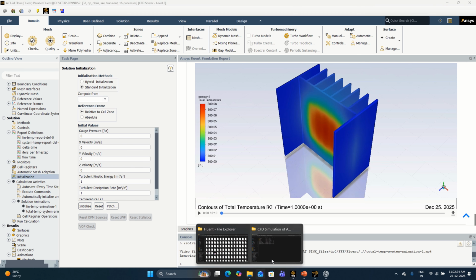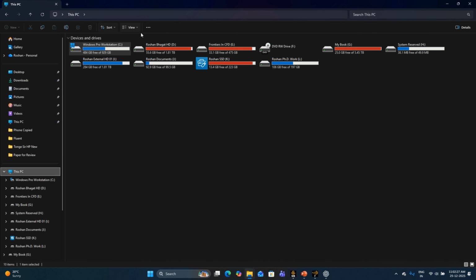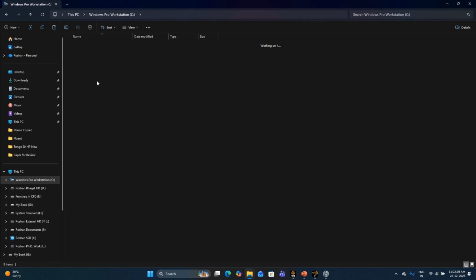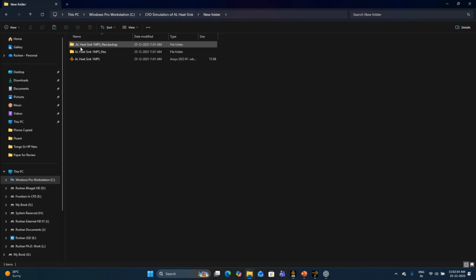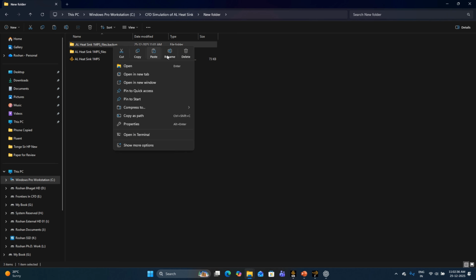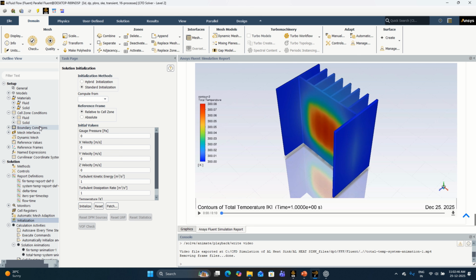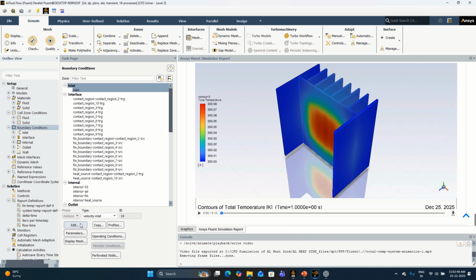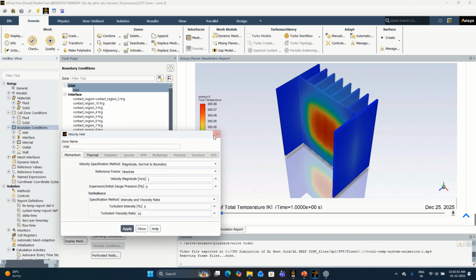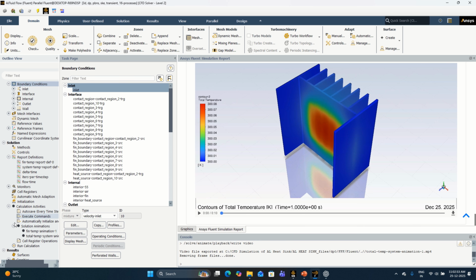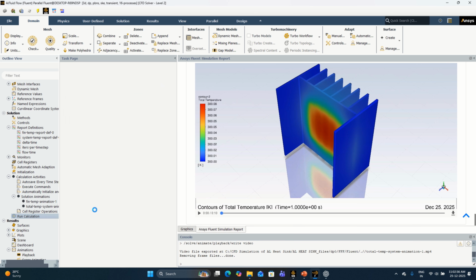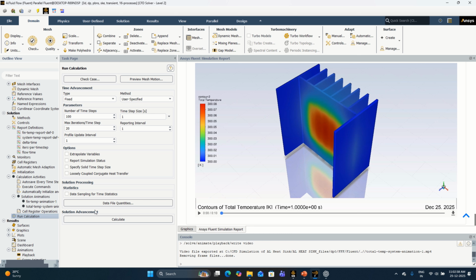Now go back to your respective folder. So this is the new folder where we are doing it for 1 meter per second. This backup file I will delete. Then one more time I go here and click on initialize. Once it is initialized with the new boundary condition, that is 1 meter per second as a velocity, we'll run the simulation again. This is the simple step that we can follow, and everything remains as it is. We don't need to change anything else.